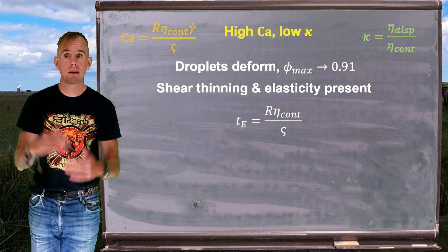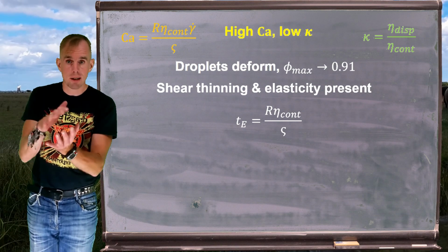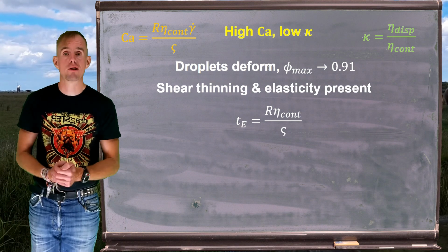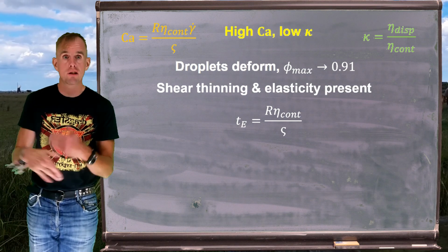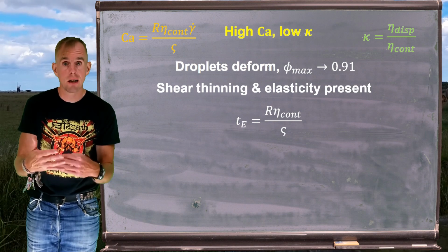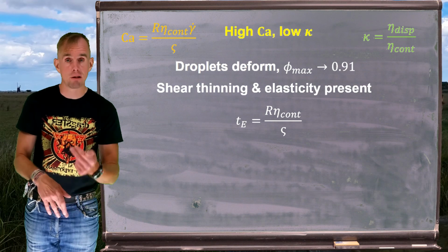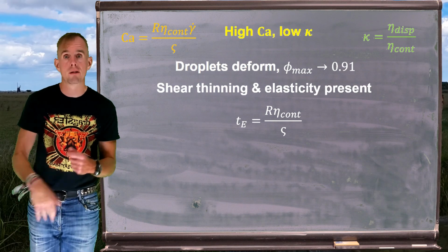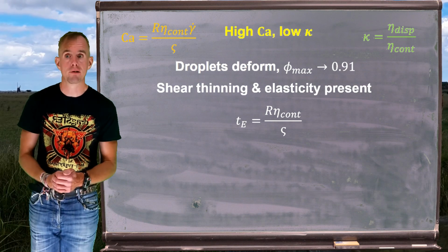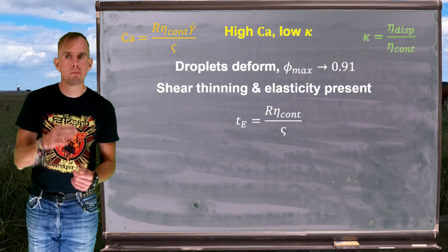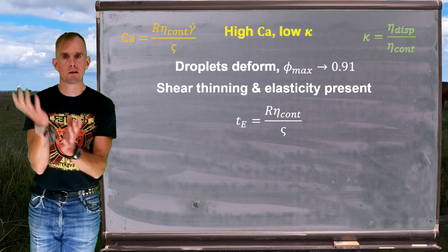So what we also see are some other physical effects. We see shear thinning. As phi max increases, we get that shear ordering. And remember, we talked about shear ordering in suspensions and said this can give rise to something that looks like shear thinning, because the packing fraction, phi over phi max, decreases with increasing phi max, and that results in a decreasing relative viscosity.